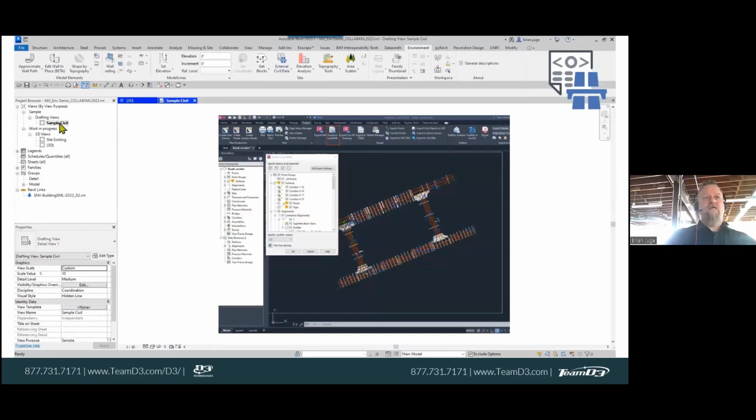I had a question come up on this topic at the moment: how can we collaborate with other files like Civil CAD? I think we kind of answered that, but just to play it out here, on this screen we can export a LandXML file. That looks at the specific corridors and alignments you're bringing in, and which portion of the alignments.